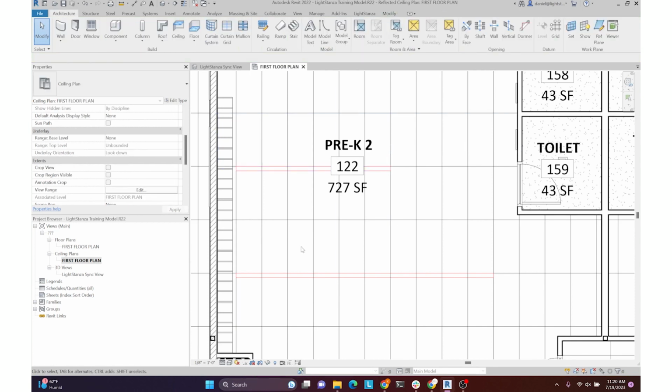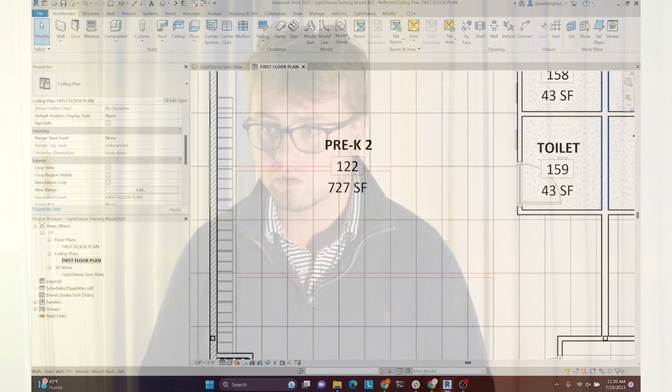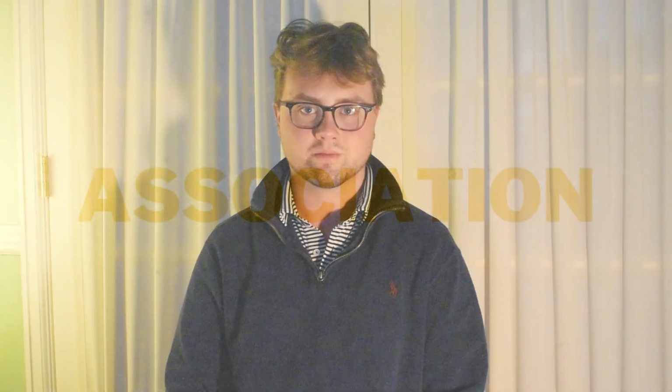And that's all I need to do with the direct input method to scale that IES file for these 2 different lengths of linears. While this method does work, and is great for somebody newer to Revit, I'm sure you can see how this can get tedious over time, since it requires you to type these parameters in every time you place a new fixture. Let's now take a look at the second method, which we like to call association.